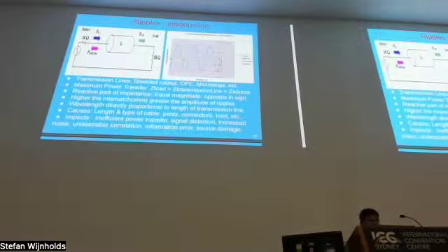If the impedance has a reactive part also, then to correct that one, we should have equal magnitude and opposite sign. Then the higher the mismatch, meaning if 50 ohm goes to plus or minus 10 ohm or 20 ohm, the amplitude will increase as the mismatch increases. The wavelength of these ripples is directly proportional to the length of the transmission line. As the transmission line length increases, the wavelength of the ripples also increases.